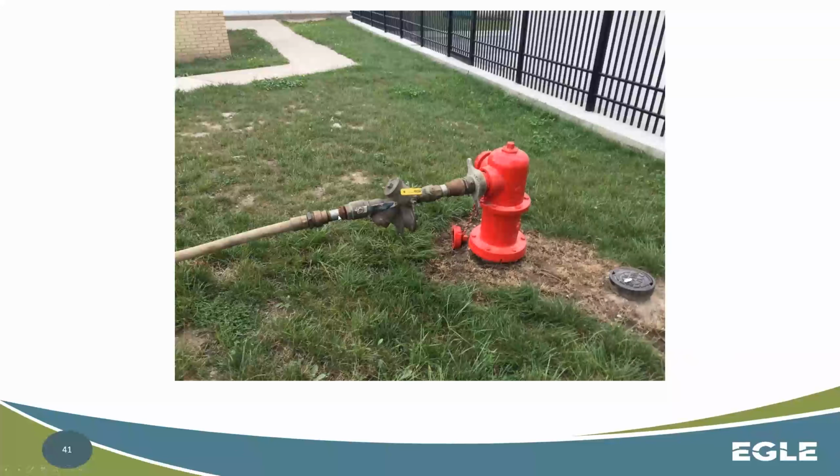The only note I would have here is that this is getting to be a pretty long lever out to this point here, or even this point here. So that's putting a lot of strain on that nozzle. And so you might want to actually have some kind of little makeshift stand or a 2x4 or something here to just take some of this weight off. But this is a good example of how you can isolate a use of temporary water in such a way that it doesn't cause an issue for the hydrant or water system.